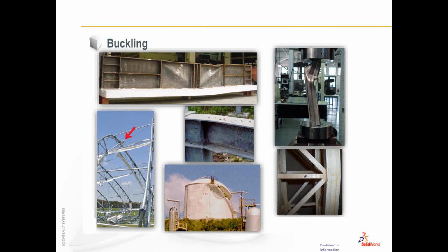That's something we would typically think of when we think of buckling. But also we may have the silo, like in the bottom center picture, that may undergo buckling, or a webbed type of structural member that may undergo buckling as its main failure mode. And a lot of times that's not considered in the design of those types of structures.